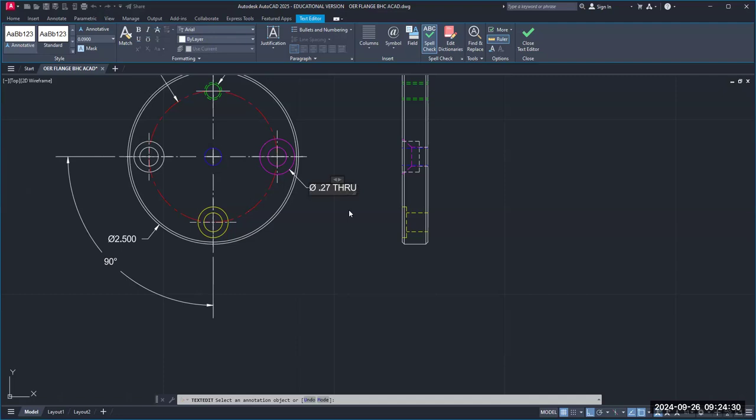That's the abbreviation for it. Enter, and you see how you got the symbol. I'm going to do CSK, which stands for countersink. There is a way of putting that symbol, but I'm running out of time. So just type in CSK, means the same thing.